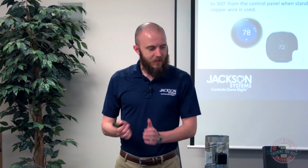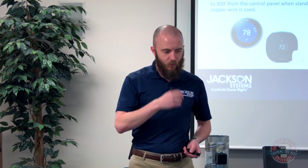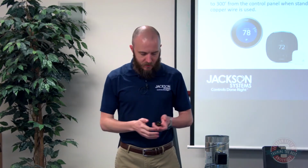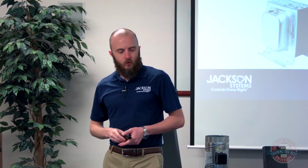What else? Thermostats and zone dampers can be located usually up to 300 feet from the control panel with standard 18 gauge wire. That's a pretty standard thing. Always use a separate 24 volt transformer rated at the proper VA to power the panel, dampers, and zone thermostats.